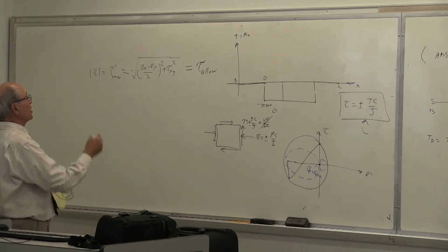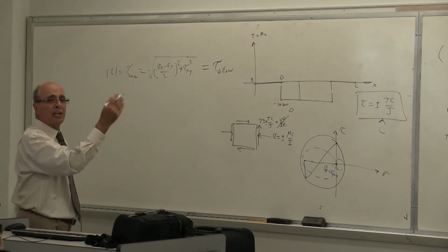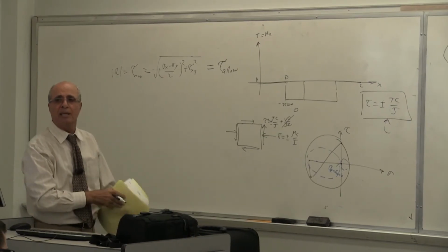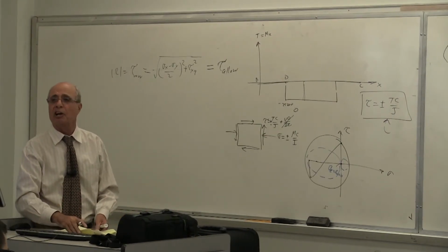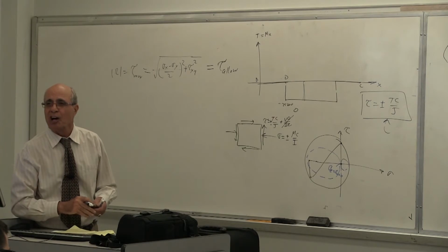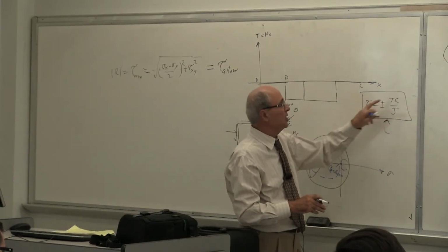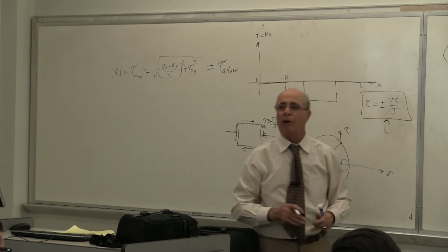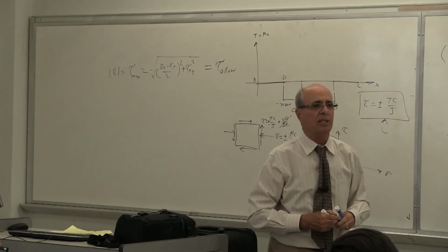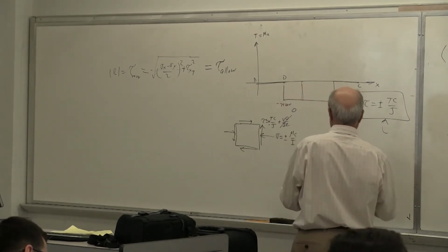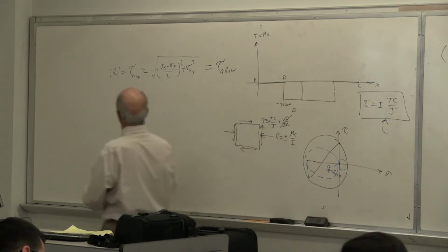Now let's finish this sentence. This has gone through every step, step 1 through step 7, but the only thing I have not decided yet is the size, because if I had the size, I could calculate J, I can calculate C, I can calculate tau equal to 5,000 psi. Everybody remember what I'm saying. But I don't have the size yet because I want to simplify that.